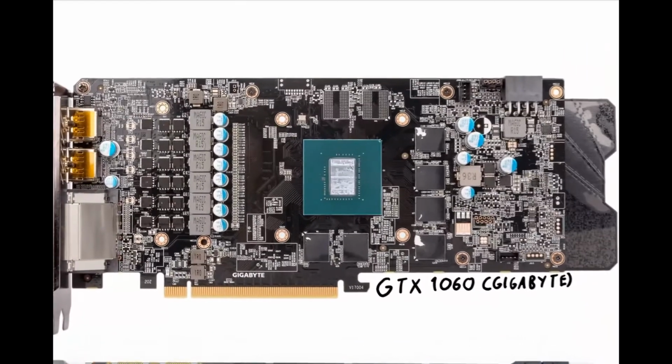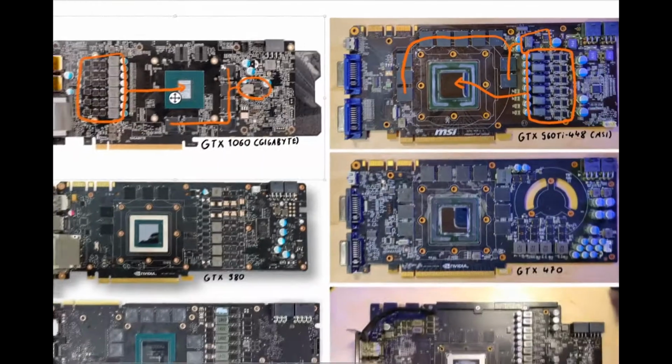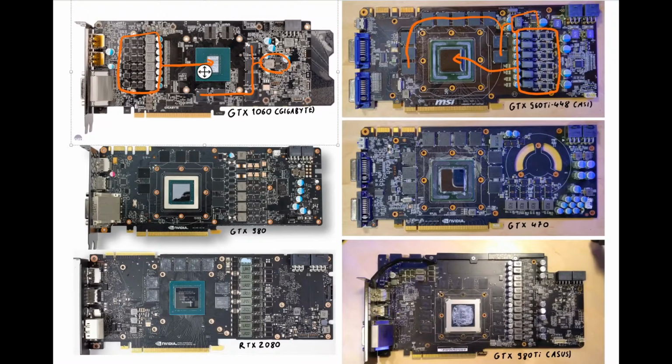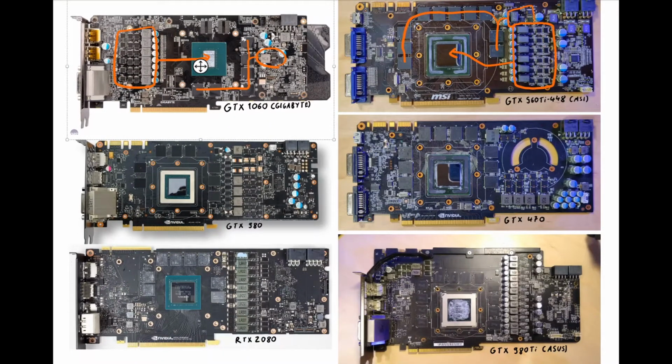So then here on the 1060, we have vMem again, so that powers our 6 GB here, and then here we have vCore, and that's actually a special layout. On all the other pictures vCore is on the right side, because most of the time the core is slightly to the left, mostly above the PCI Express connector. So you have the most space on the right side, which is where you would put a VRM.